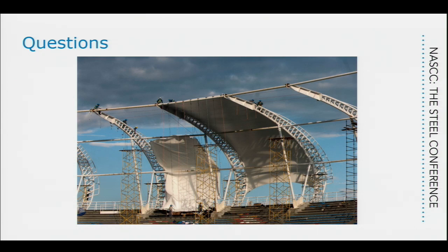It gets unfolded in the field, and think of this as your steel structures or your tilt wall panels, where you design them for the in-place condition. But we also have to say, okay, if we're going to lift it from this end, make sure that it doesn't rip when I lift it from a single point because it's so heavy. But you lift it with a crane and you start to anchor it in place.